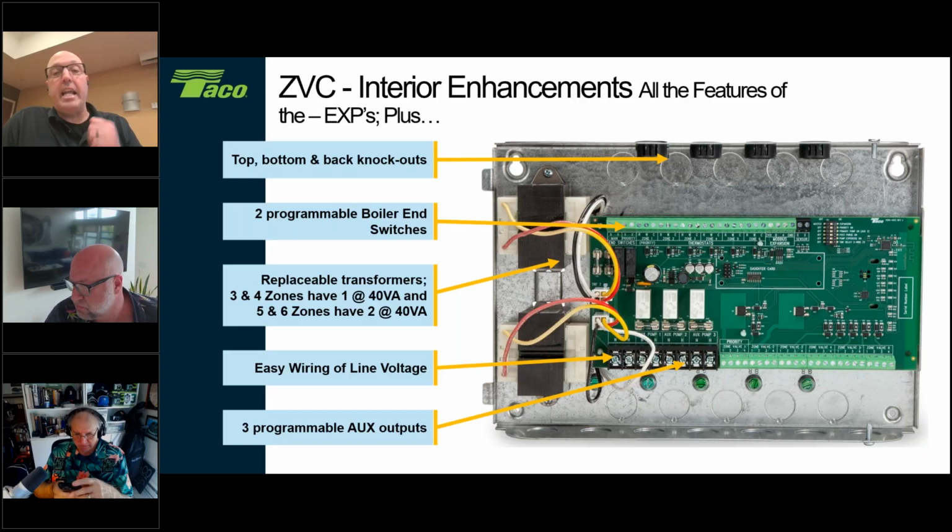And here's the big difference. In the ZVC-4s, the pump outputs were dry contacts. They were non-powered terminals. You had to bring power in. The Dash 5 model, these are now powered, because 99.95% of the time you were using it to run a pump that was line voltage. So we figured, hey, might as well put power to them now.